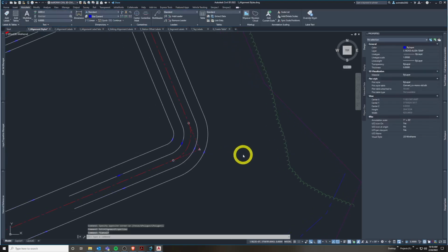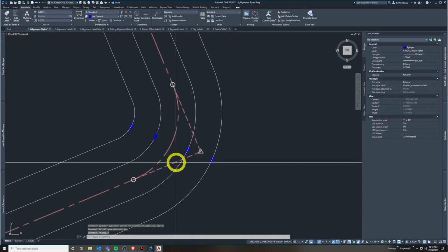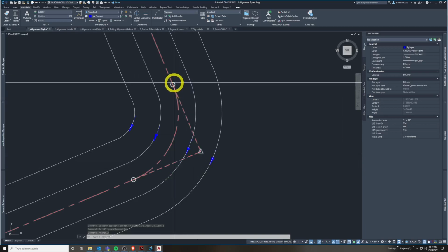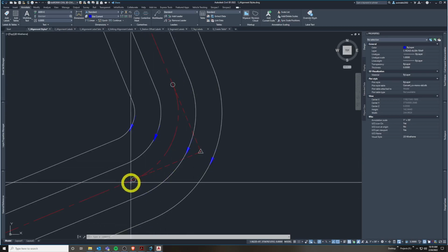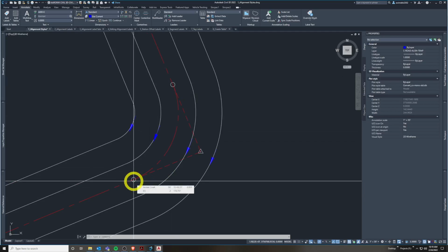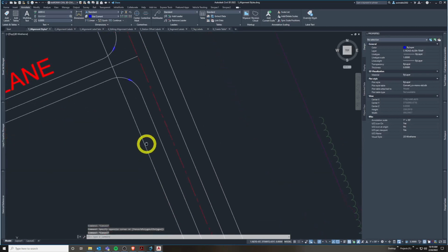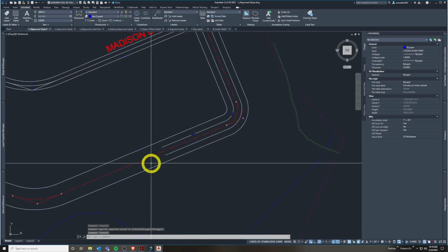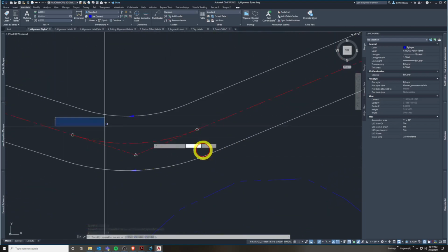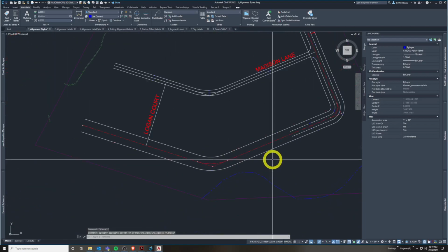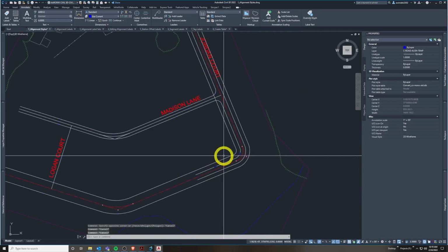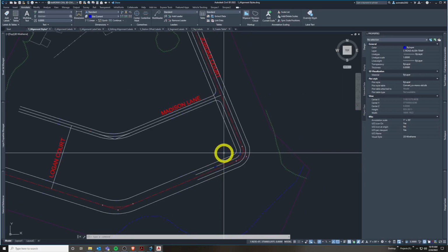It adds some different annotations. It's now showing the extensions to the point of intersection, the PI. Here's your PC, point of curvature. That's where the curve starts. Here's where the curve ends, the point of tangency, returns to tangency, aka straight line. And it has different note markers showing. So it has slightly different symbology. Very similar though. Red phantom line, but these areas on the curve look different. So I'm just showing you the power of different styles basically. That's what we got going on here.